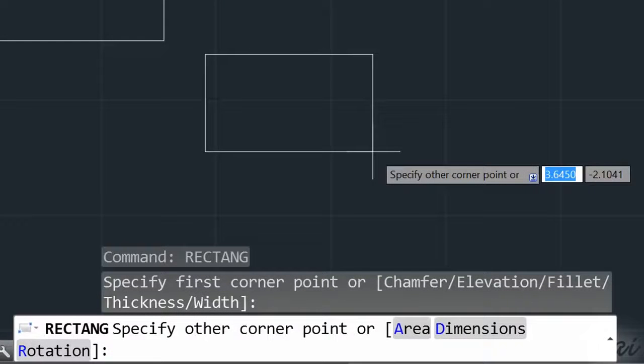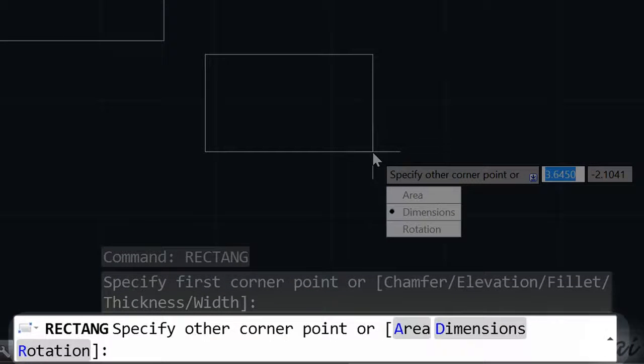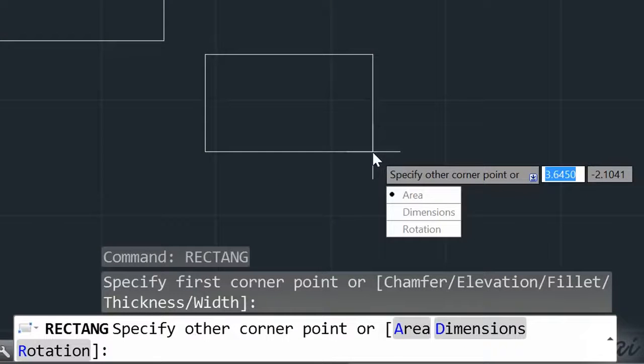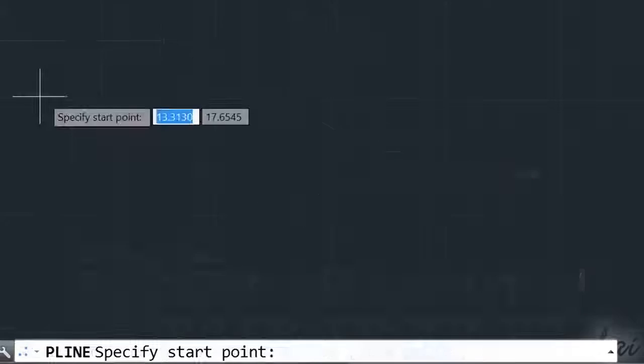Plus, while using the tool, the command line shows you the same extra options seen before in the dialog box close to your pointer. Such commands have some letters in blue. This means that if you type such letters and use Enter key, you will enable the option related to such letter in the command line. While you draw,